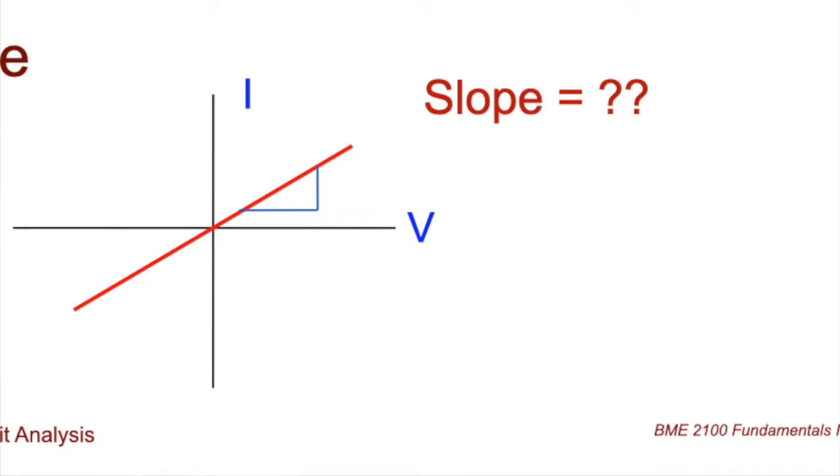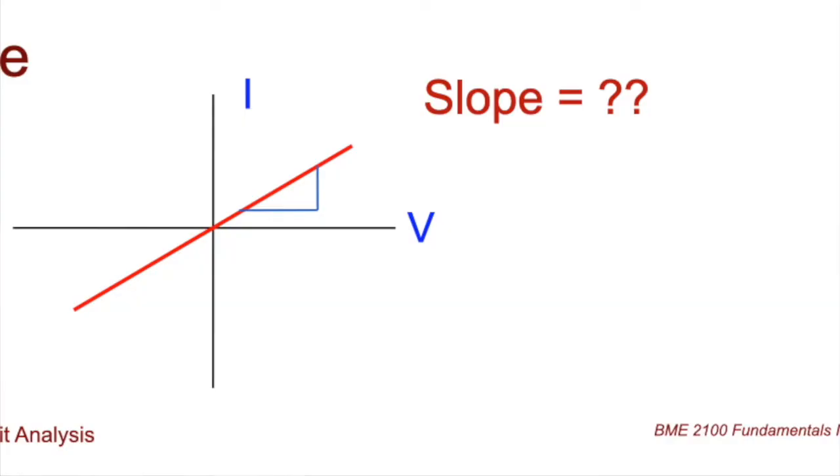So we can adjust the voltage, different values, record the associated current. In this case, we have both positive and negative values. Voltage can change polarity, and with that, the current direction will also change. But we get a straight line. And we also know, what do we care about when we have a straight line? We care about the slope, and we care about the intercept. So in this simple circuit, the intercept goes through 0, and the slope is what? Well, the slope is current over voltage. And current over voltage is the same as conductance, G, 1 over resistance. This is just like what we saw in this situation with flow.